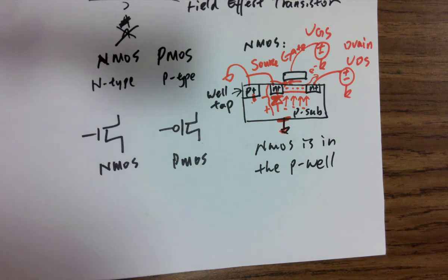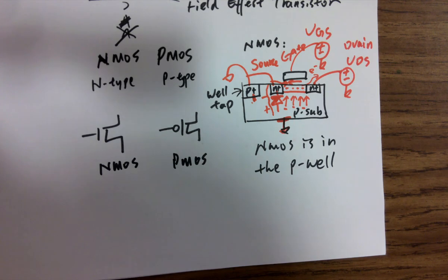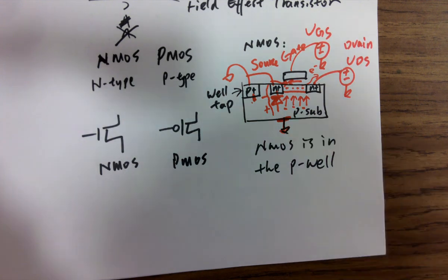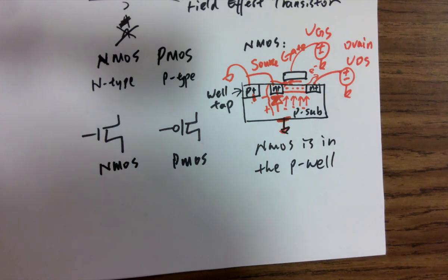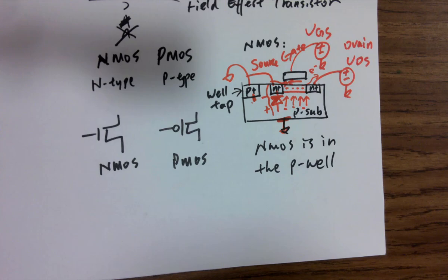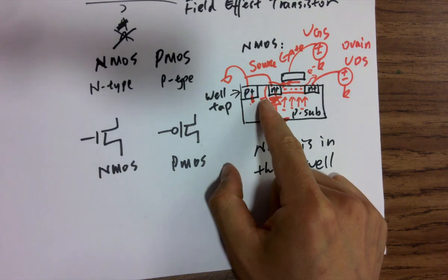It's physically extracting electrons from it, because the electrons flow in the opposite way. So it seems like I'm injecting something, but actually you're taking something out of the channel, right? Physically, electrons are going away, and you are getting a thicker or thinner channel? This is a question, you guys. Thinner or thicker? You get thinner. So physically the channel is getting thinner because this current is pulling electrons out of it.